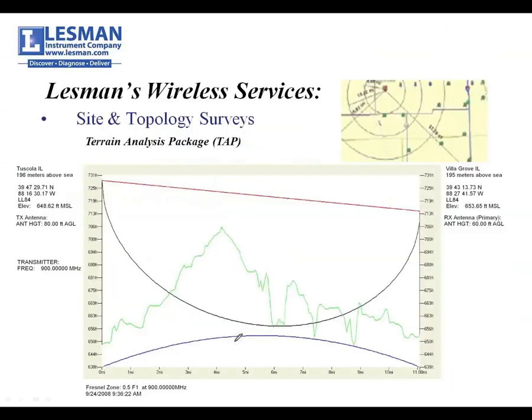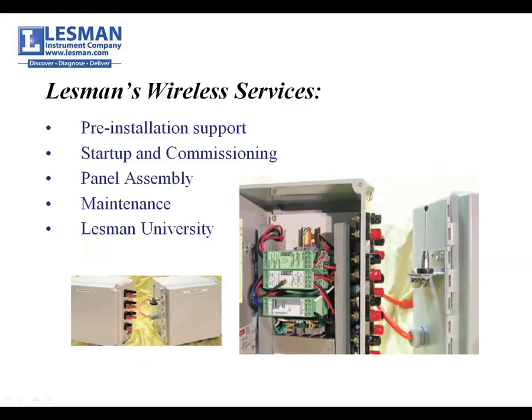So I'm running a little bit long. I'm running a lot long. When we take a long shot, we have software that allows us to see the curve of the Earth in blue, the actual topology of the environment in green, the radio shot, the lower half of the football in black, and this is the line of sight between the antennas. So we can accurately determine where and how high to put antennas for a long-term outside shot.